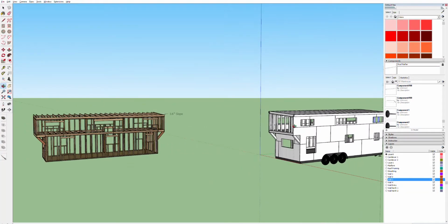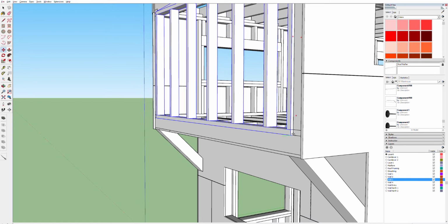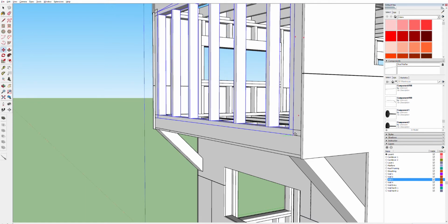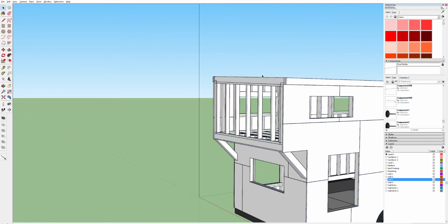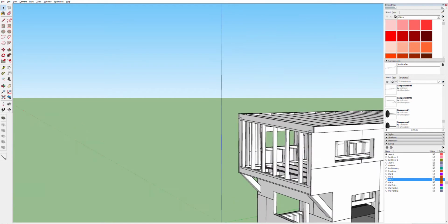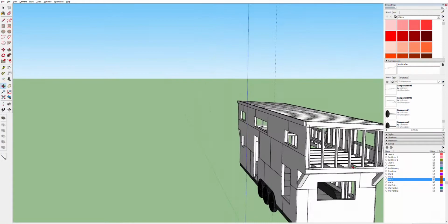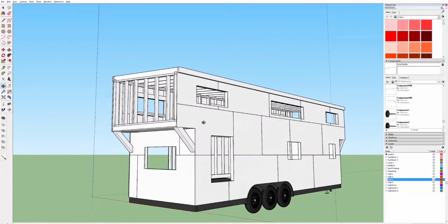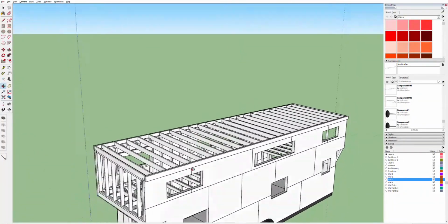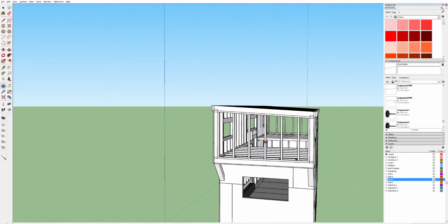There are, oops, this end wall was a little bit too far. Looks like 3.5 inches too far. So I'm going to move that in, locked to green. And I'm sure that was 3.5 inches, and it was. Okay, there we go. Save that guy. There we go, guys. These are our end walls. And the next step is going to be to sheathe them and then sheathe the roof. And then we can keep moving from there.